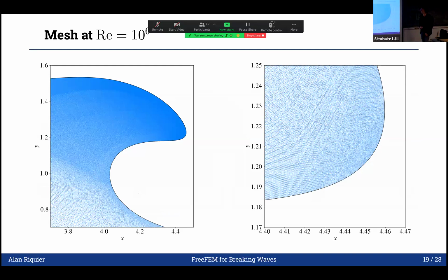It might be a good idea to use mesh adaptation in order to decrease the number of triangles, but still have enough precision near the tip. We're currently working on this with Georges, back in the room. It might be a good idea also to use a mesh adaptation scheme to go in 3D, because with this method, it's already very slow, and I don't see any way to go in 3D without increasing the computational time to numbers that cannot be tractable.